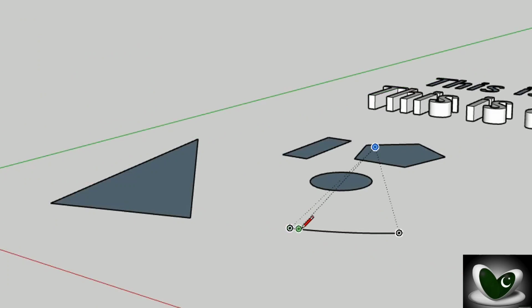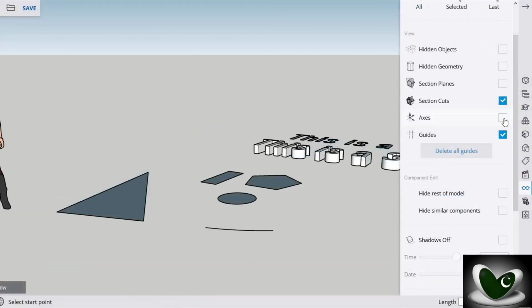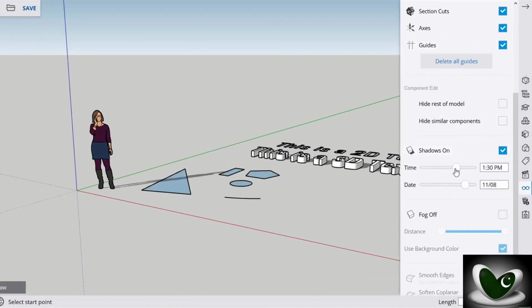Besides these colors, you also get snappings to the most important object key points, such as colored circles for vertices and nodes, squares for points on sides, and rhombuses for points on faces and filled areas. Also, dotted guidelines may appear, indicating perpendicular directions, intersections, and extensions over objects, sides, or axes. From the Display panel, you can manage the aids to use and also apply visual effects on the preview, such as shadow and fog.